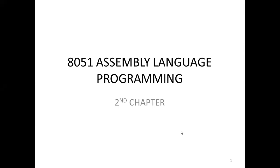Okay students, I am going to start with the next chapter, that is the second chapter, and the name of the chapter is 8051 assembly language programming. In this chapter, I will demonstrate some of the registers used in the 8051 with simple instructions, move and add. The move instruction is used for copying data from one register to another, and the add instruction is used for addition purposes.